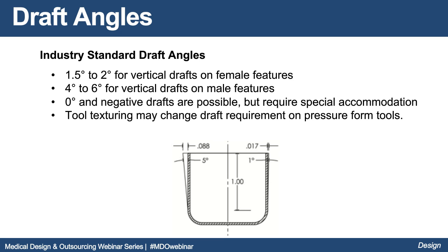The other thing is tool texturing. This is a conversation that comes up quite frequently because we're molding in color and texturing the tool itself. That tool texture is going to dictate what draft. Most people have seen or heard of Mold-Tech. Mold-Tech is going to give you a requirement on that draft. If that requirement's not followed, just like in injection molding, you can see marks from drag, or when that part's ejecting from the tool if you don't give significant draft. Again, we can go to zero or negative by pulling that wall, and that actuating slide can also be textured. So that's it for draft angles.